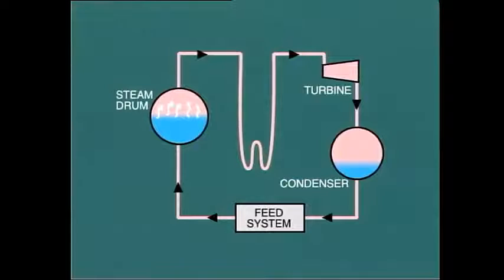Once in the boiler, some of the hydrazine vaporizes and passes over with the steam, moving through the turbine and into the condenser. Here it may help scavenge any oxygen that is present in the condenser. One problem with hydrazine is that it can be a health hazard, and therefore certain precautions must be taken in handling its feed system.